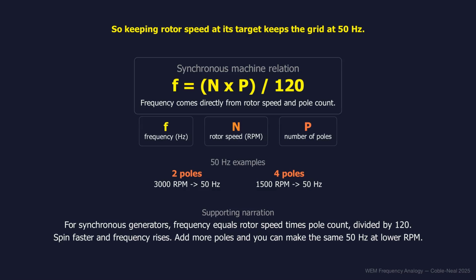First, let's establish what frequency is. In alternating current electricity systems, electricity is traditionally generated by thermal generators, for example steam turbines, that use a fuel to drive a magnetized shaft that rotates inside a fixed stator, inducing an alternating voltage. The relationship between rotor speed, generator design, and the resulting electrical frequency is given by this equation. F is for electrical frequency in hertz, N is for rotational speed in revolutions per minute, P is for number of magnetic poles, always an even number.